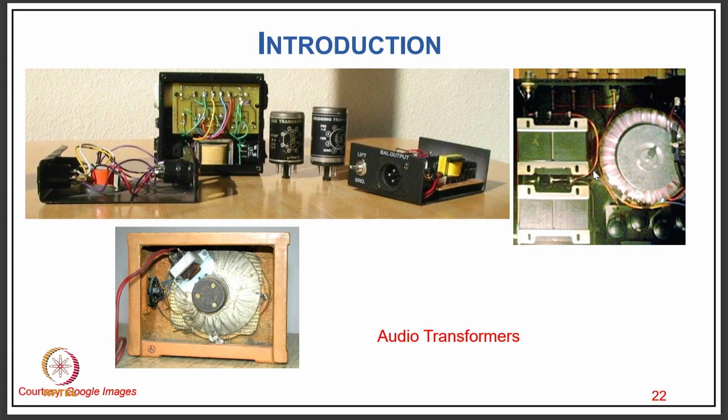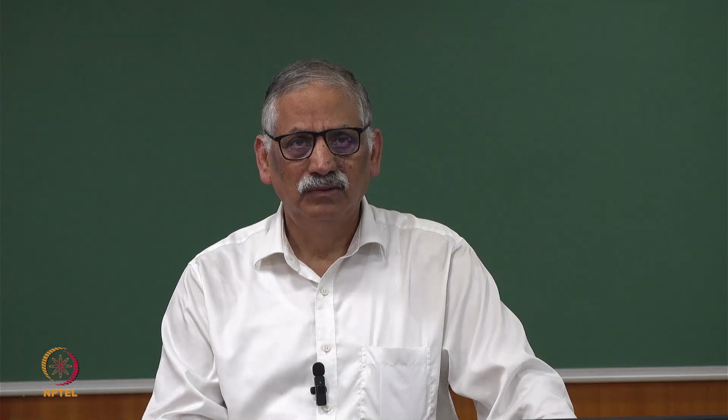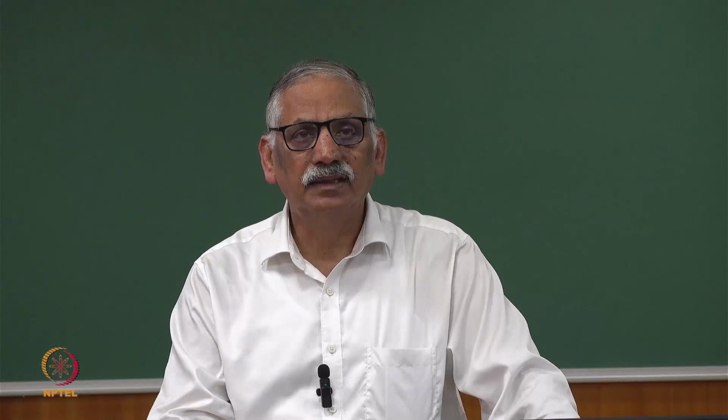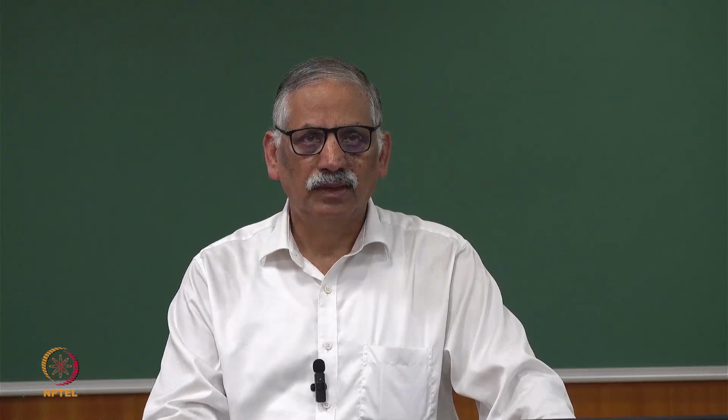Then you have different audio transformers, which are used in typical electronics, all the amplifiers and sound amplifiers. This is an interesting application, which we call impedance transfer using transformers. What we do here is, we might have a mic or speaker of around 10 watt, hardly having about 3 ohms, 5 to 10 ohms, which gets reflected as 5 to 10 kilo ohm on the amplifier. So that the amplifier is not loaded.